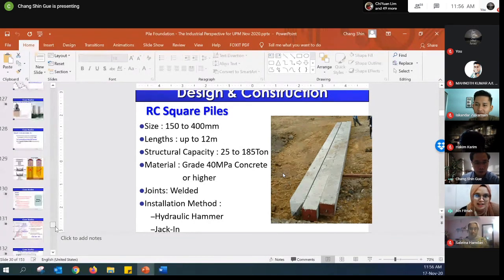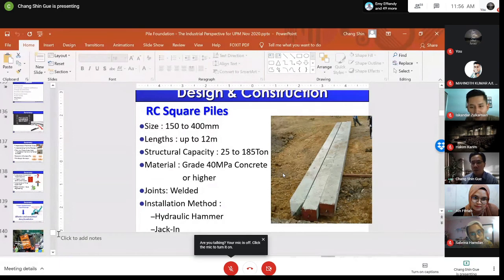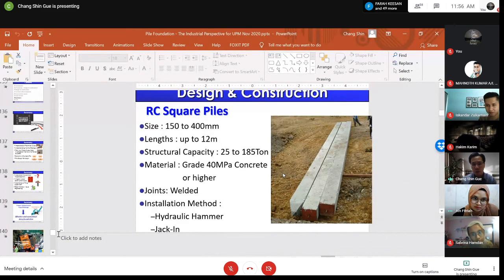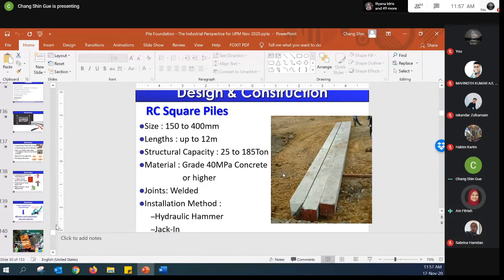Okay. And the last one, how long is the instrumentation monitoring carried out? The instrumentation monitoring depends on the critical work, for example, if you are constructing a basement excavation or foundation. If you finish your critical work, meaning whatever you do after this will not induce further settlement, then you can actually stop. But normally, once you finish your critical work, you will still monitor for another maybe one or two months while the other work is going on, to make sure there is no additional movement, and then you can terminate the monitoring. Okay, thank you, Dr. Gwen. Thank you.